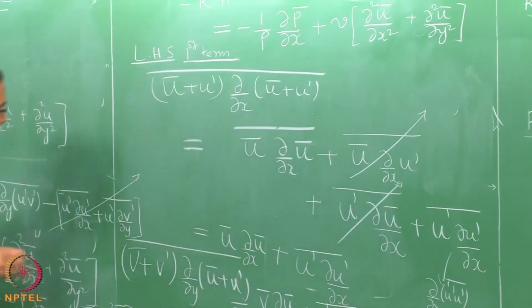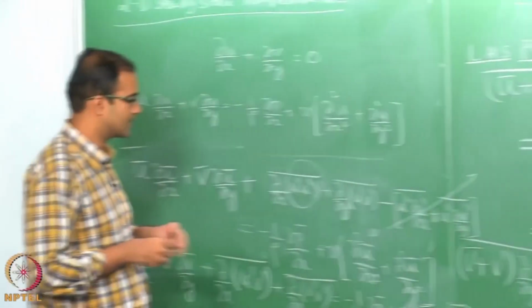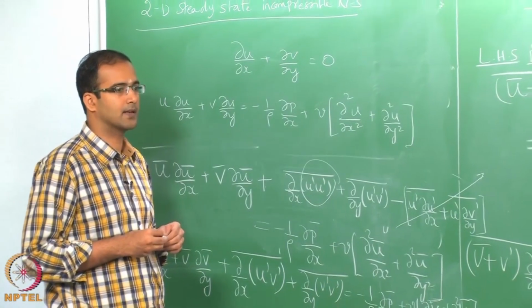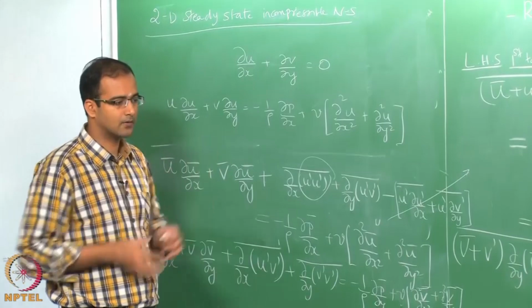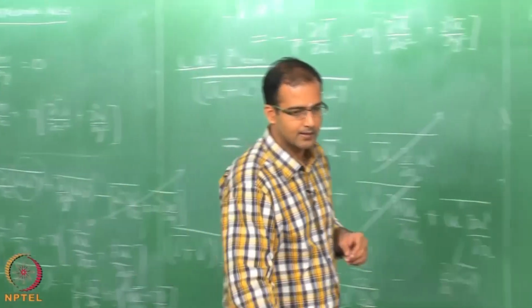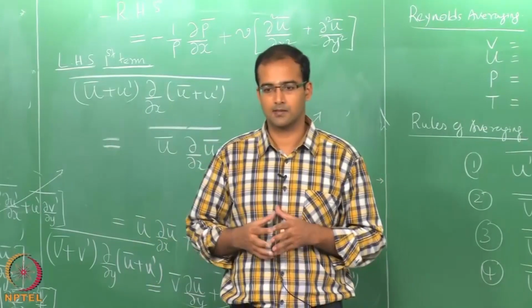What I suggest you do is the same thing for the energy equation also, and see what the Reynolds averaged energy equation is. Tomorrow we will list down all these RANS equations together and then see how we treat these turbulent stresses.